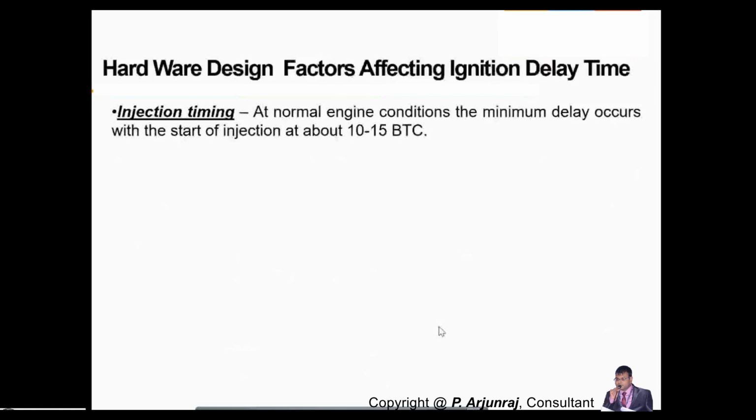So some hardware design factors will also affect the ignition delay time. First one is injection timing. At normal engine conditions, the minimum delay occurs when the start of injection happens 10 to 15 degrees before top dead center.